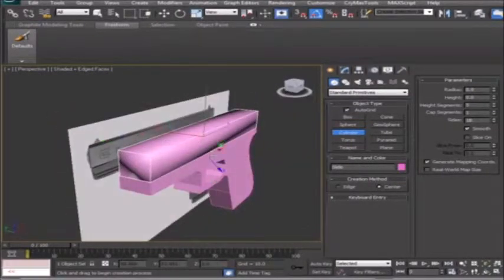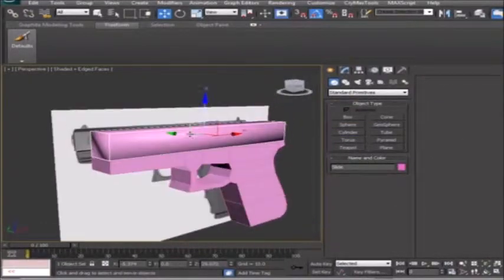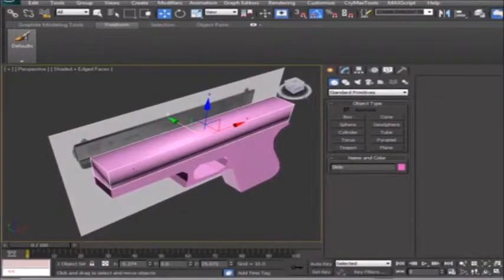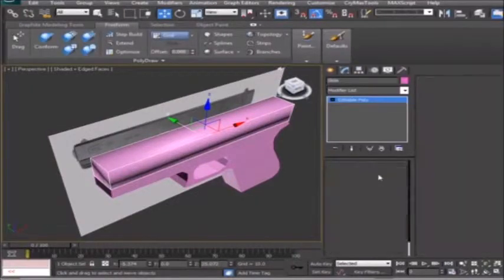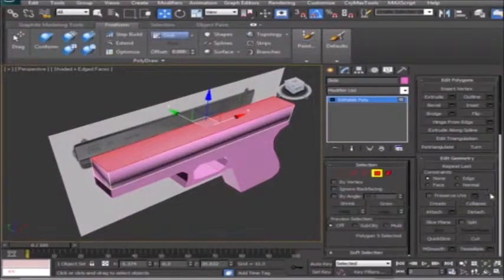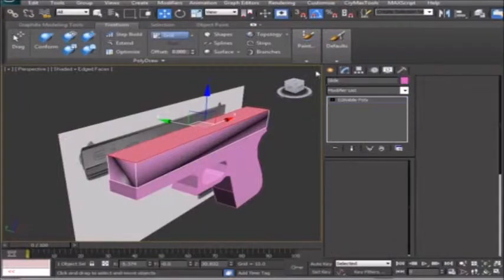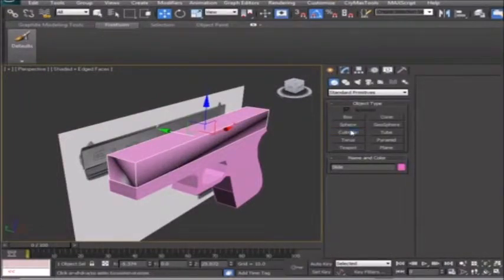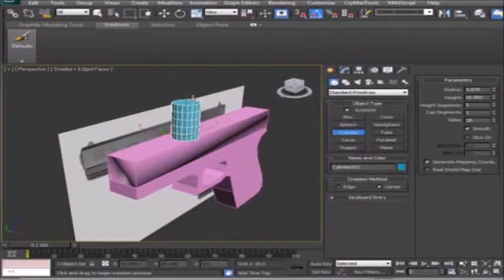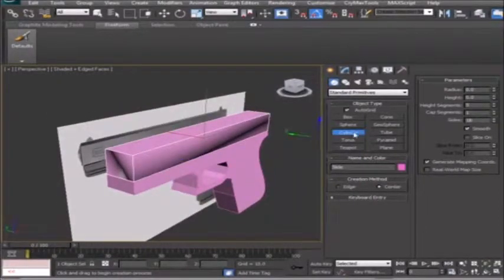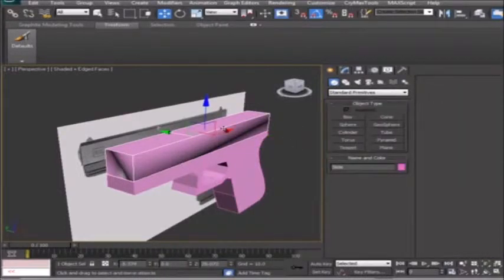So if you need to draw something right off of a surface and it's giving you a weird angle and it's not letting you do it, select the object you want to draw off of, get the face that you want to draw off of, and just clear that smoothing group by unchecking a smoothing group. And now when I go to draw it, it's perfectly flat even if I'm right on the edge. Okay, as soon as I get to this one that's still smooth, you can see it curves that. So just keep in mind that it does take smoothing groups into account.